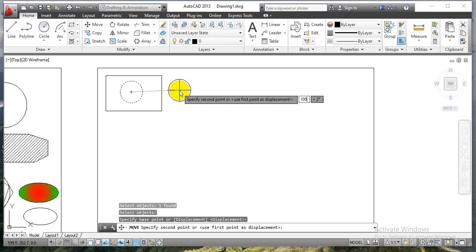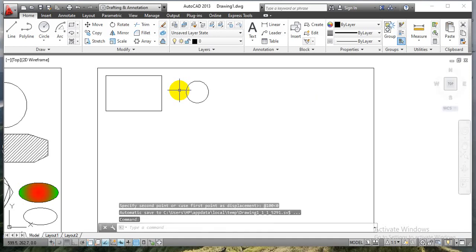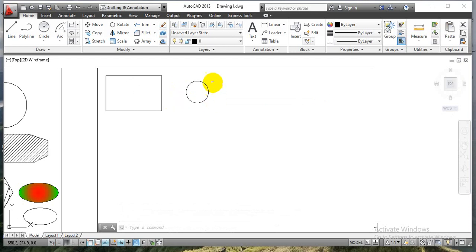Okay, if I just press tab button, the second rectangle is get enabled. Over that you can mention the inclination. Now I can enter the inclination to which we want to move that previous circle. Now let me move this circle horizontally so that I can enter 0° value over there and press enter button. Now you can see the previously we have that circle into that rectangle that I have moved to this outside that rectangle. If I just undo this construction by pressing Ctrl plus Z button over the keyboard, again we will jump to the previous construction.